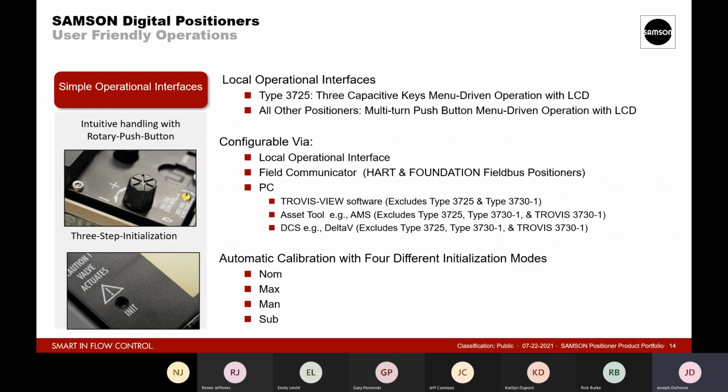This is often used on rotary valves. For example, if you had a centric lined butterfly valve and you read the manufacturer's recommendations for setup, often they will say that you don't have to go to full 0 degree closed to achieve that tight seal. You can have a few degrees offset, up to, I've seen like 10 degrees, where that resilient seat will achieve the 0 leak, and yet you're not loading and creating a larger breakaway torque. So you could do that.